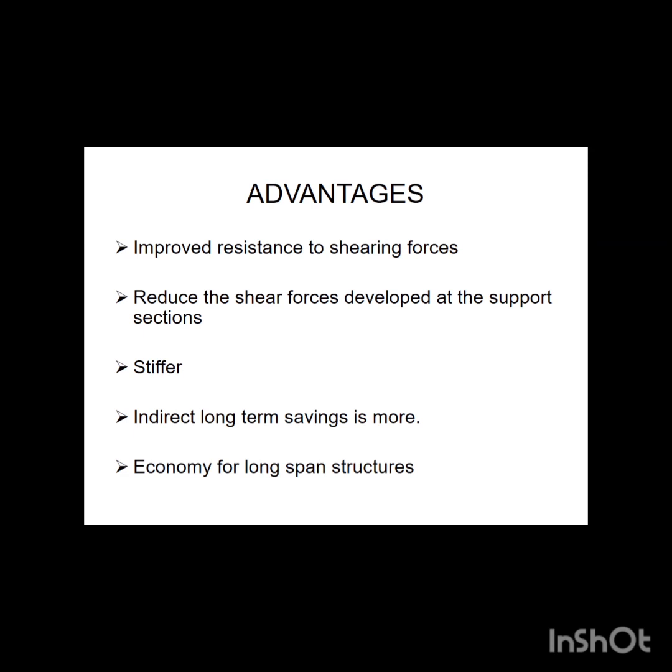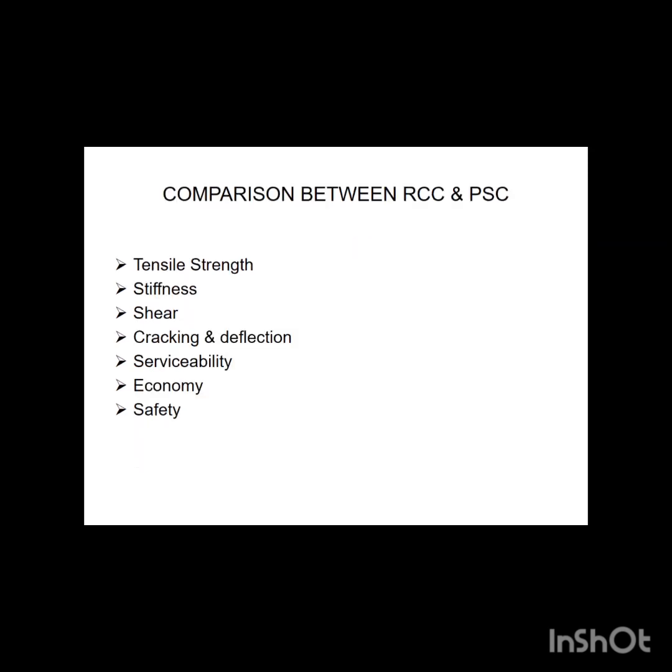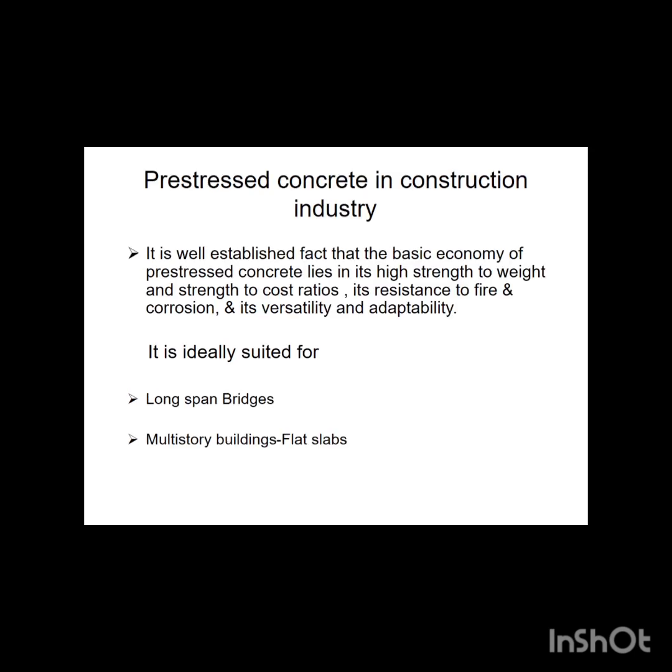Advantages: improved resistance to shearing forces, reduced shear forces developed at the support sections, stiffer members, and indirect long-term savings. More economy for long-span structures. Tensile strength comparisons between RCC and PSC. Tensile strength, improved stiffness, shear strength, cracking and deflection ability, serviceability, economy and safety.